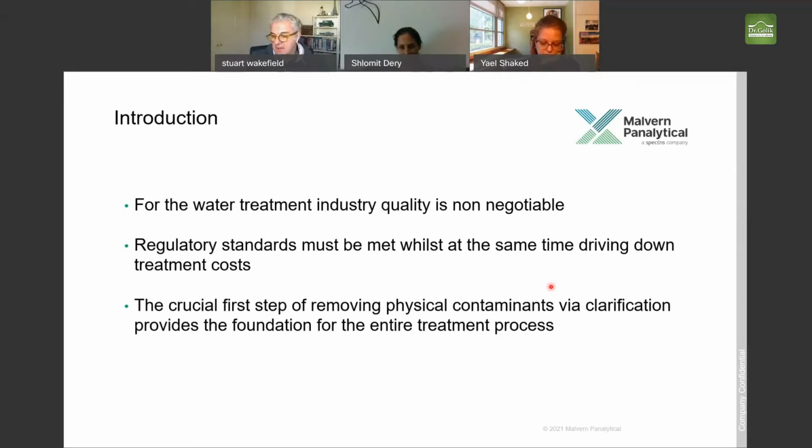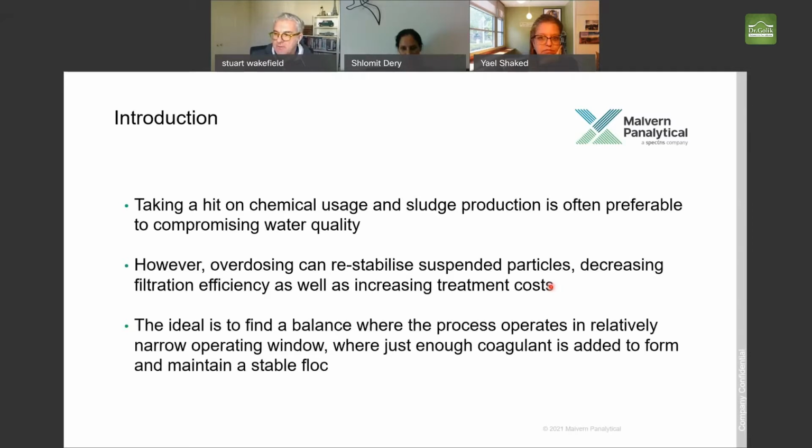And the first step in most of the processes of these water treatments is typically adding chemicals to aid in clarification, so that the suspended organic material flocculates prior to sedimentation techniques in your process, or direct filtration, depending upon what your process is. Very often, a lot of people say that we don't want to have too much sludge production, but often that is preferable, and they will spend more on chemicals to stop that.